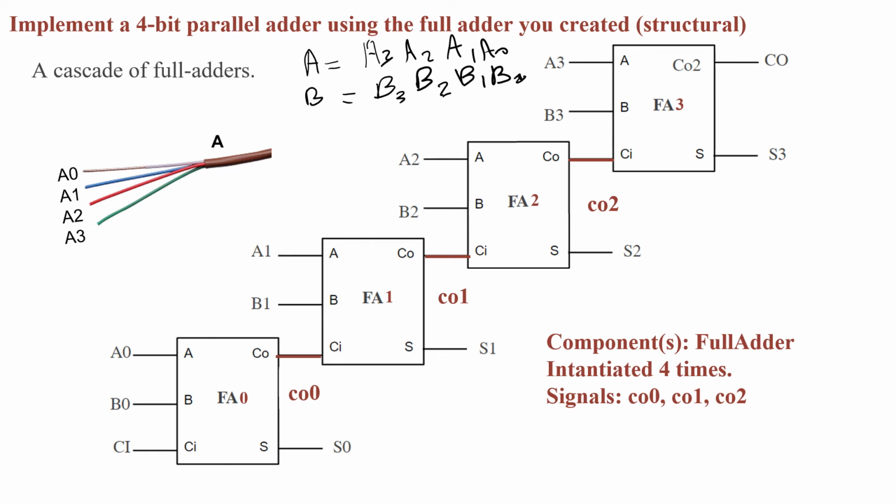The same goes for S and B. So we can say that for the ports, we only need A, B, and S, and finally Cout, where A, B, and S are each consisting of a vector of 4 bits. So we can only say again A, B, Cn, Cout, S are our only ports. Of course, A, B, Cn are input ports, Cout and S are output ports.